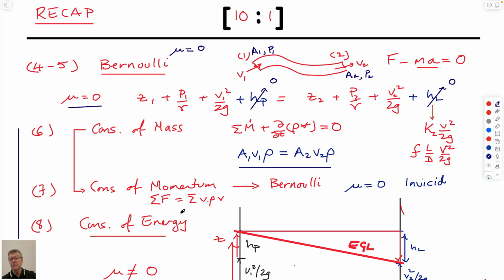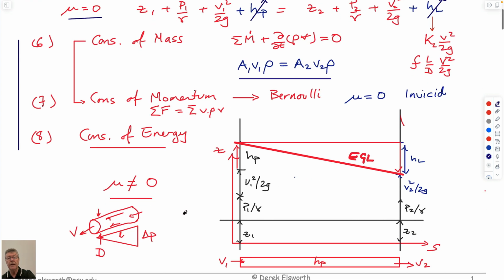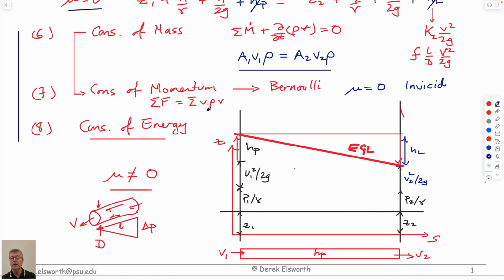And so we can define that. So this is just a much more sophisticated way of writing Bernoulli, which allows us, I suppose, to calculate what the forces are in the system. We kind of did it before. We did a jet example using Bernoulli, just by using the pressure of the jet on the ground. It wasn't quite the same answer as using this, and so we used that. Still, using conservation of momentum, it's still inviscid. There are no losses in these systems.